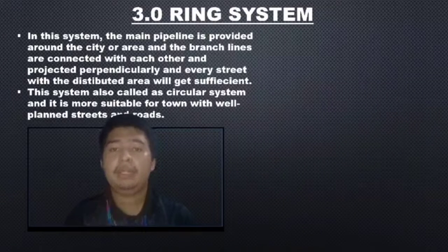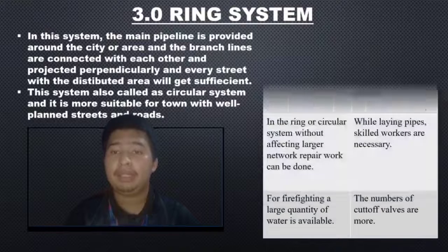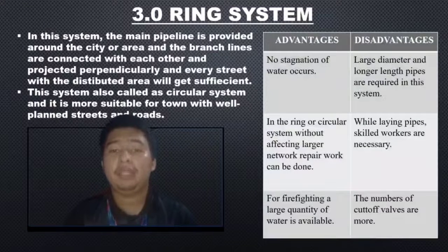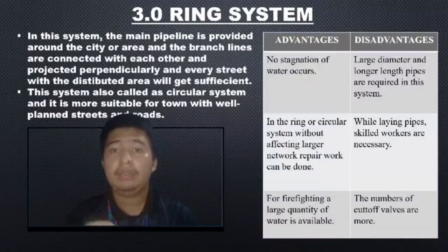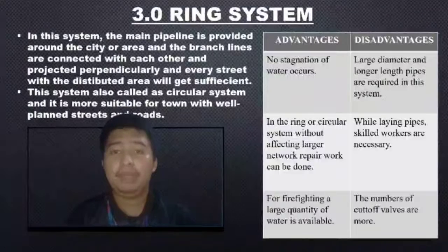And this ring system has advantages and disadvantages. For the advantages, there is no stagnation of water. Repair work can be done accurately in the ring or circular system without affecting a large network. For firefighting, a large quantity of water is available.